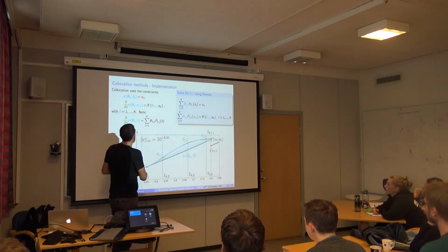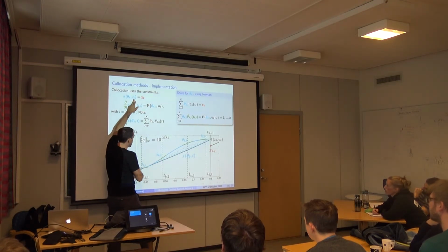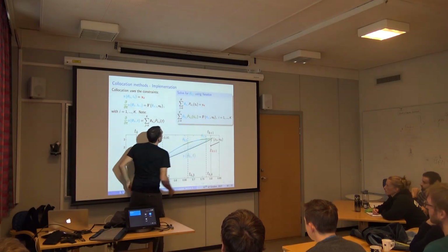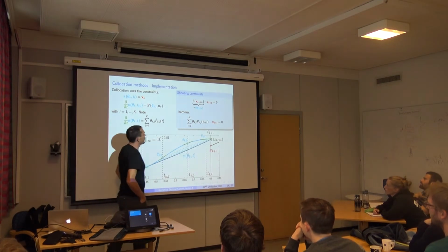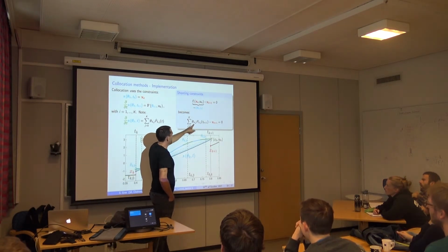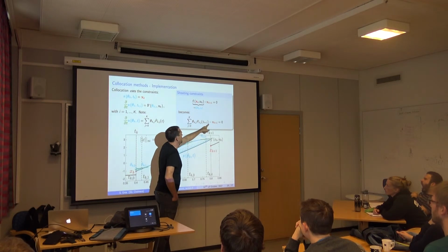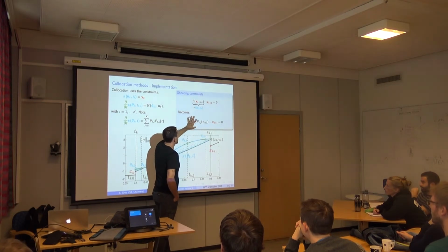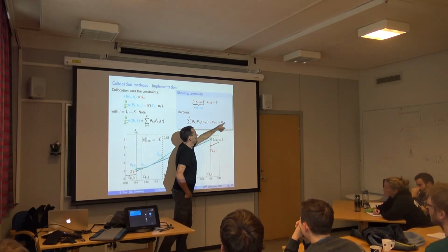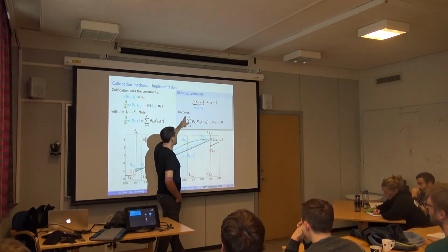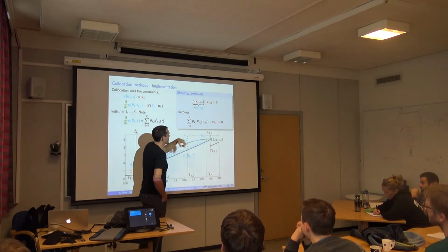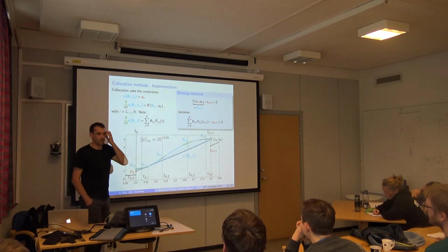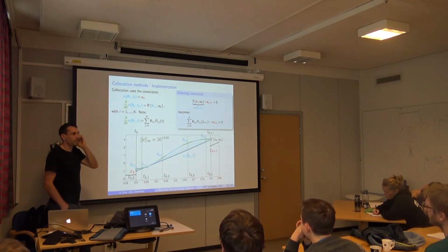So you basically take s evaluated at tk plus 1 over there, and that would give you the function f. Right, so you get your thetas from Newton, and then you evaluate this thing here with these values here. That's your function f xk uk. So in the NLP solver, you could replace your shooting gap constraints by doing that, where the thetas are given by the Newton method. Make sense?